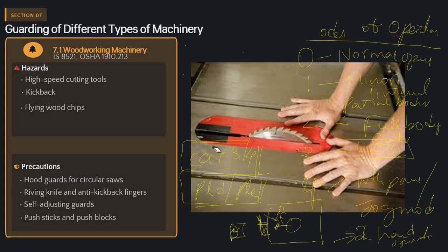Yes, it is there, the PLd, and for light curtains too. But for light curtain sensors, you should not consider them for man entry. Light curtains are normally not designed for minor intervention operations. They are designed for product entry and exit, such kind of thing. You should not rely on them for minor intervention, though light curtains have PLd and PLe also.